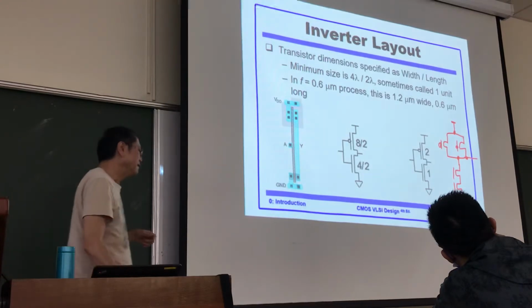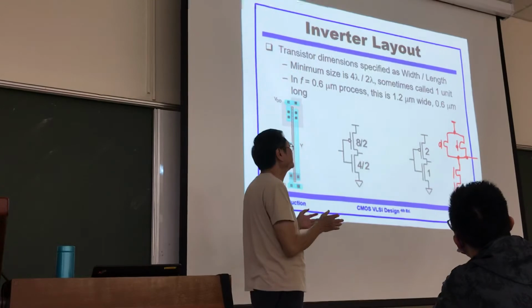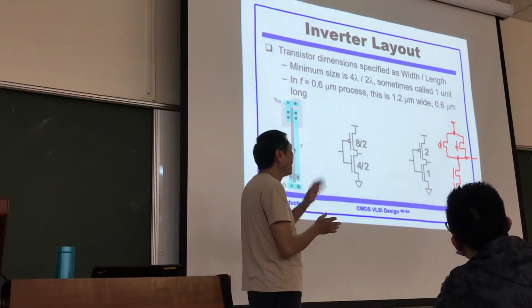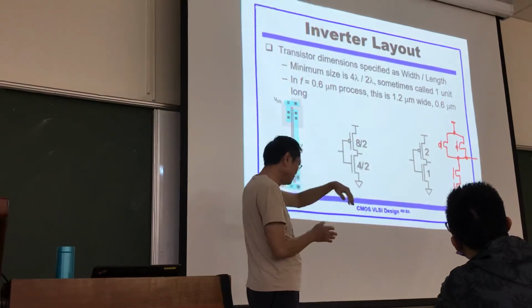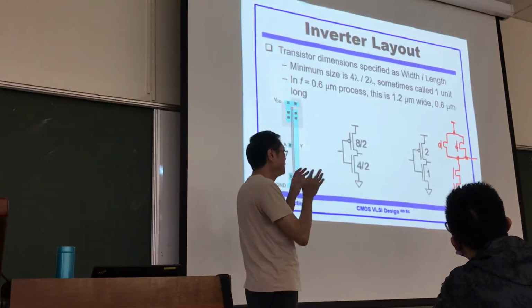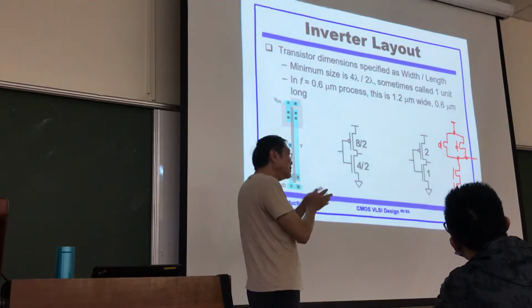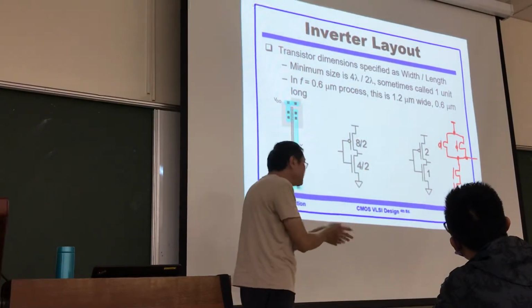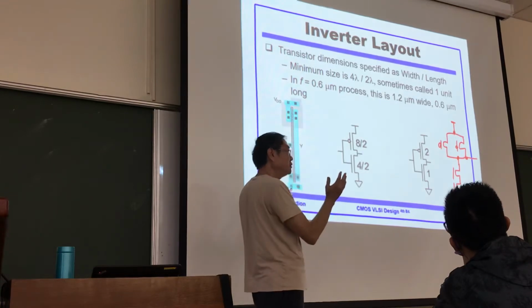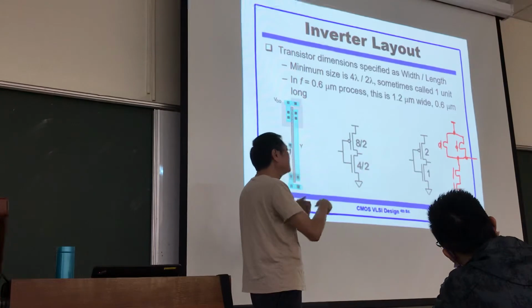We can compare the switching speed for the output 0 to high or high to low, or 0 to 1 or 1 to 0. We are taking the conservative point of view, meaning the worst case. For the worst case, given different combination of the input, 1 1, 0 0, 1 0, 0 1.